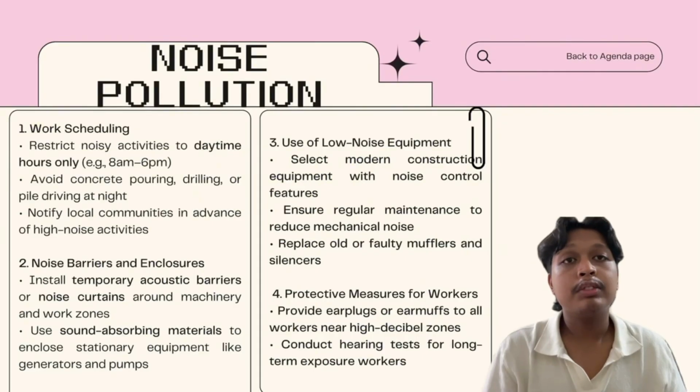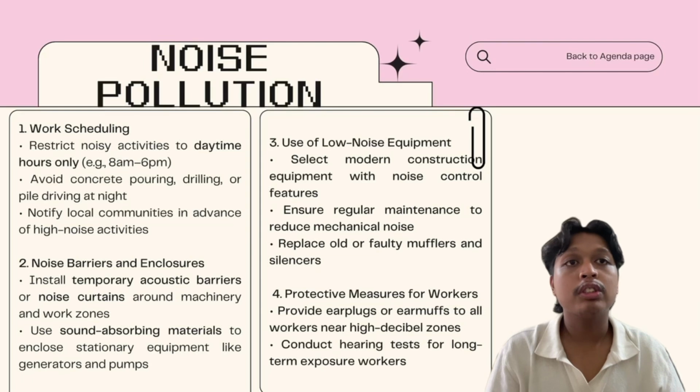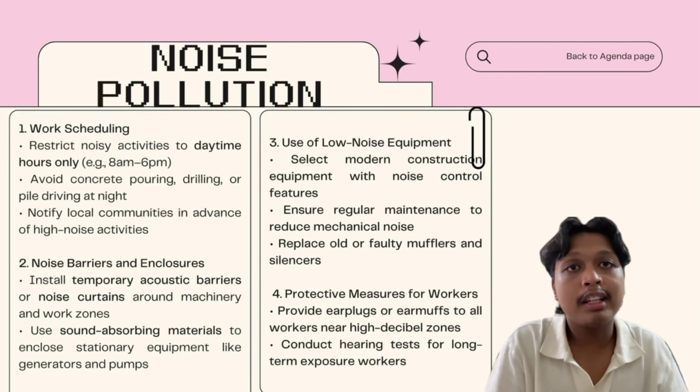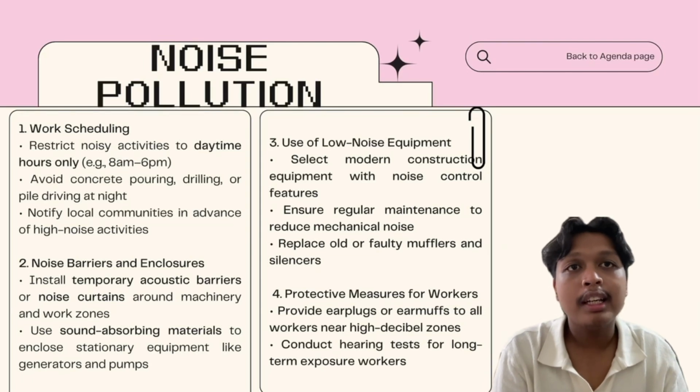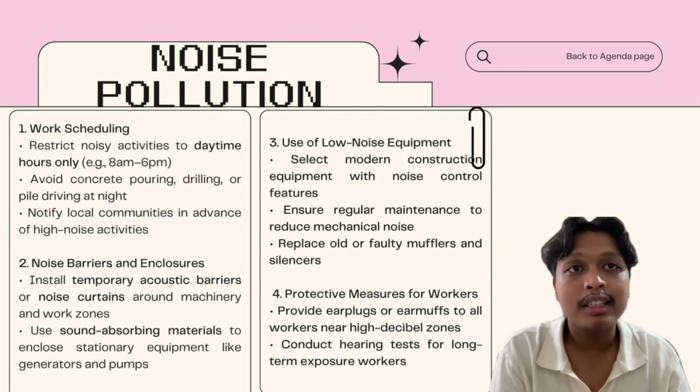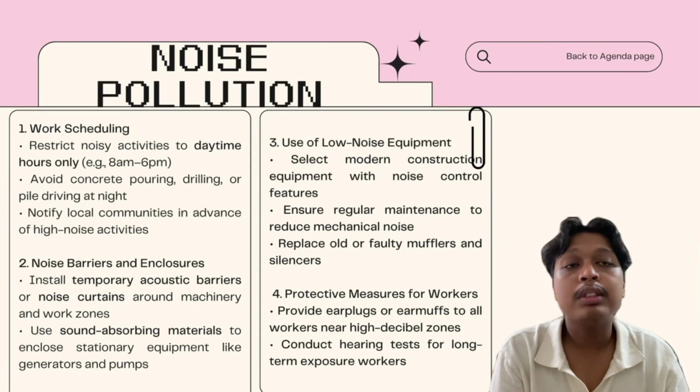For the next part is for noise pollution. Noise pollution on construction sites can affect nearby residents' health and well-being. It can cause sleep disruption, stress, and even hearing loss for workers exposed to high decibel sounds like cutting tools or concrete pumps. The first and most important measure is work scheduling.